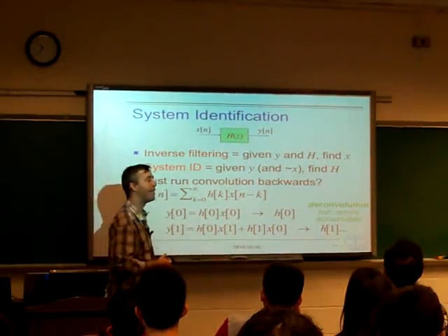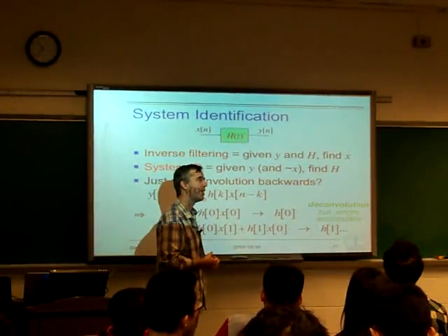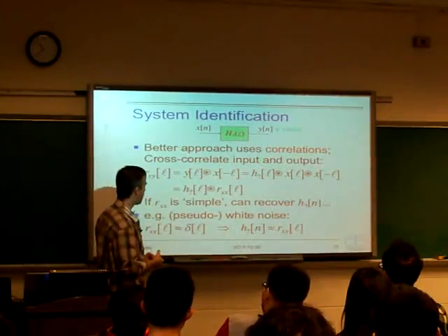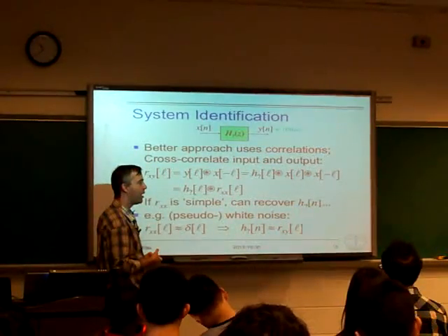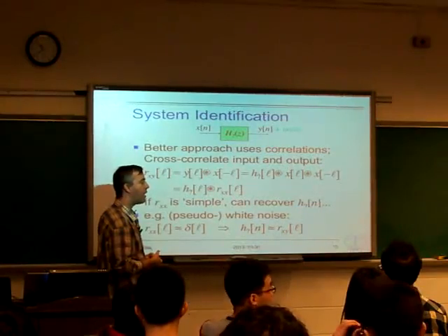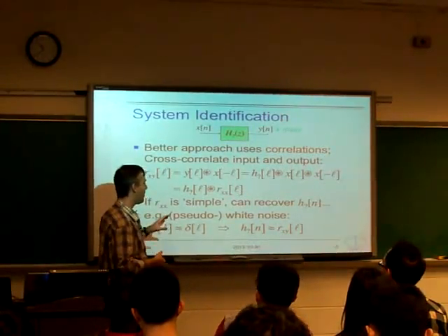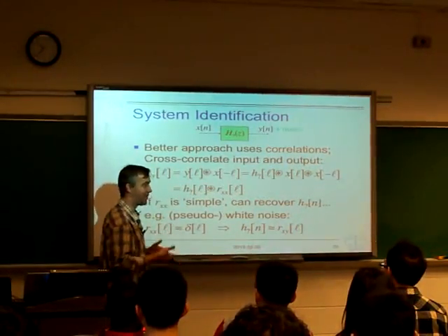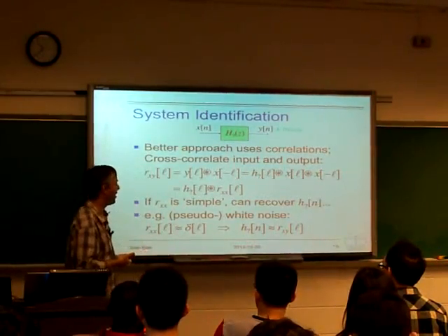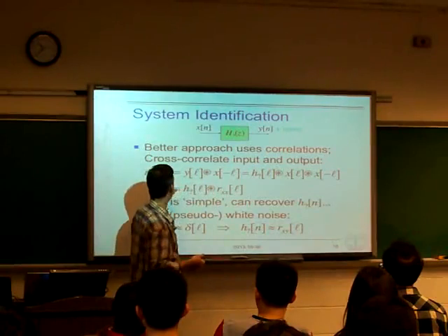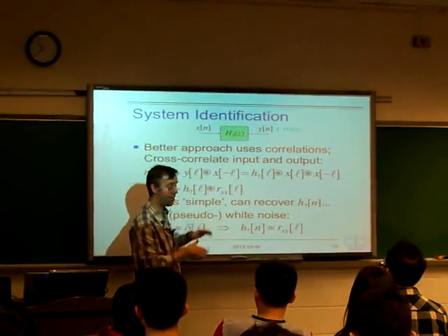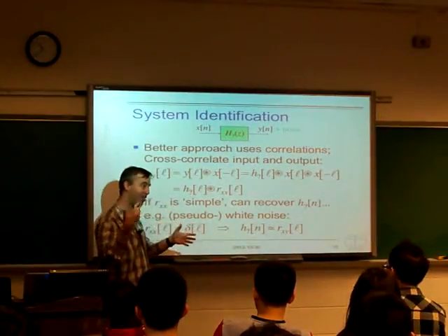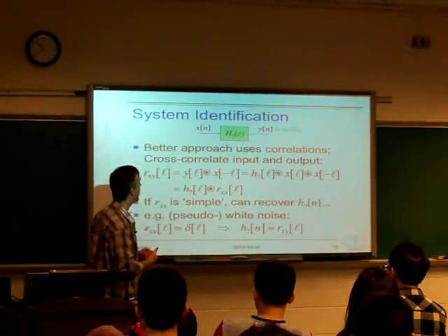Could we get better results if we work in the transform domain, rather than in the time domain? Right, so what about frequencies? These operations have exact transform domain equivalents, which would be another way to do it. So rather than calculating your actual time domain correlation using the correlation equation, we could simply take the Fourier transforms of these things and then multiply one by its conjugate, which is the same as the time reversal in the time domain, and we get the same answer.